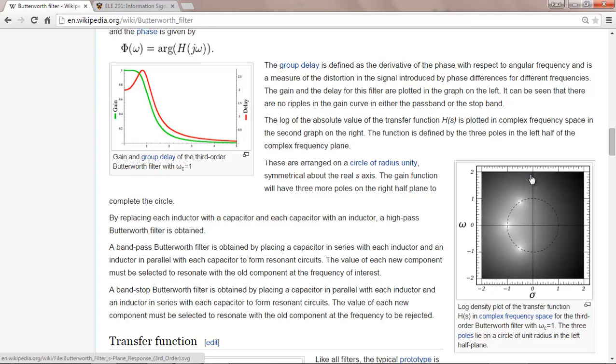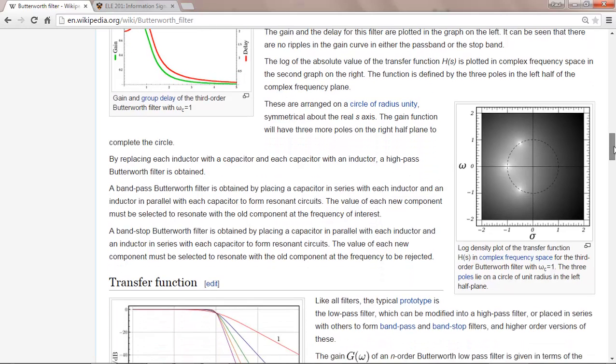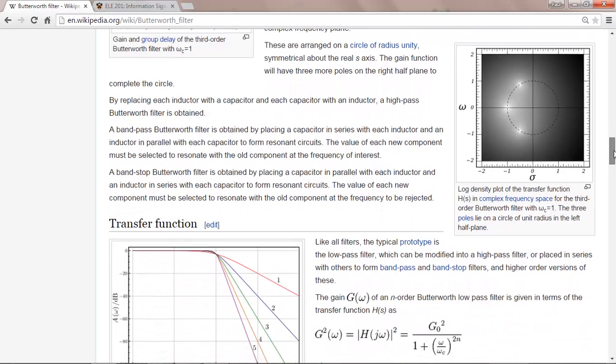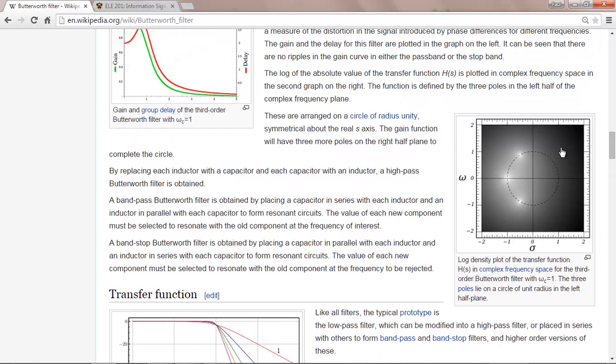If you know you only are allowed a certain number of poles or a certain number of zeros, because those correspond to how many components you would have to use, then you could place them strategically to give you the frequency response you want. And that's a part of filter design. Okay? So this is a continuous time filter designed that way. Now, you could imagine there are other techniques that give you other low-pass filters. And just to show, like the Butterworth filter happens to place the poles on a circle. Okay, so that's interesting. Higher order one would place more poles in this circle.